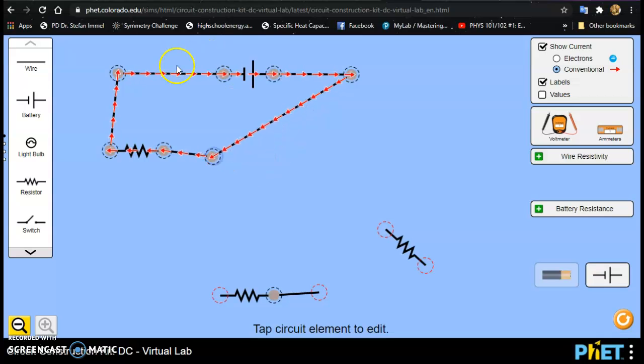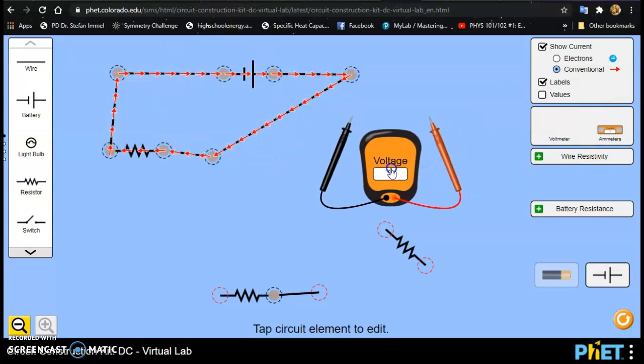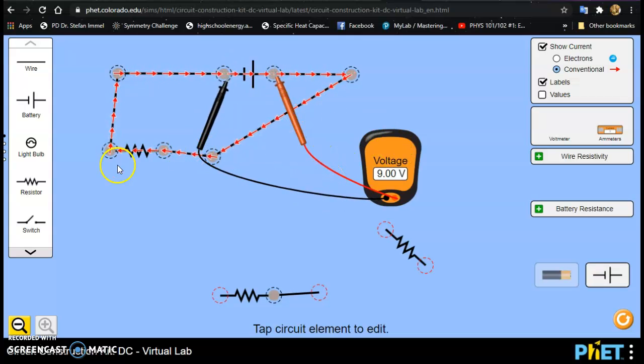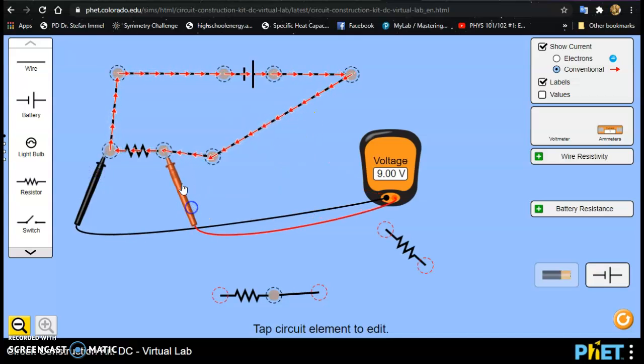So what'll happen, if I only have 1 resistor in the circuit, all of that energy, really the potential, the joules per coulomb, that's energy per unit charge supplied by the battery, will be dissipated by the resistor. So if I have a 9-volt battery, that's 9 joules per charged particle being supplied. That's a push, a drive for these red arrows representing the electrons. Then the resistor is going to use up 9 volts. There will be a potential drop of 9 volts, 9 joules per coulomb for the electrons traveling through this resistor, and then the electrons will travel back to the other end of the battery.